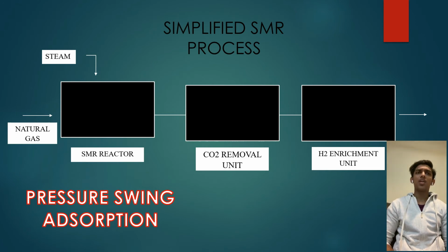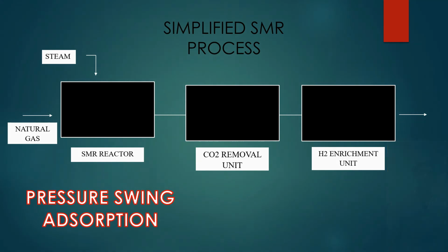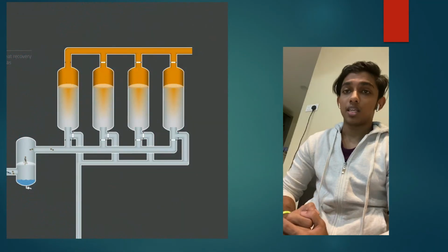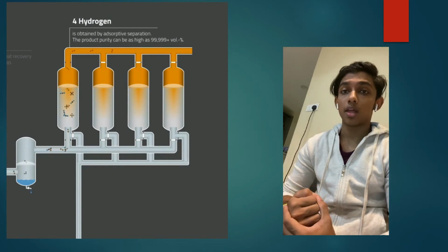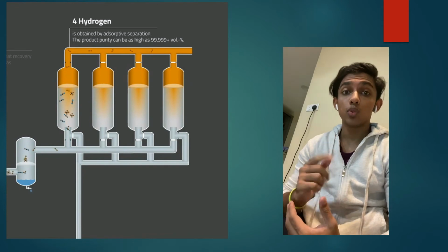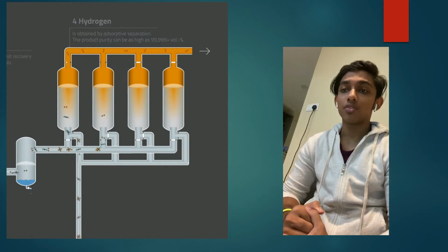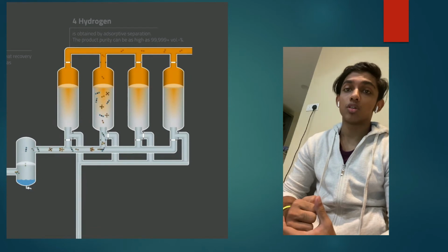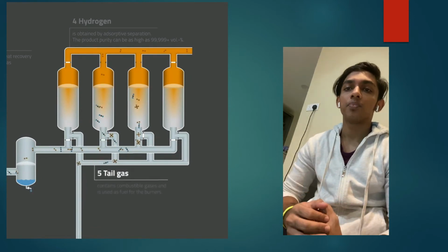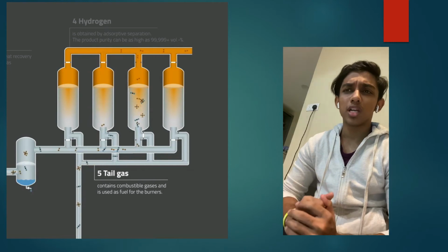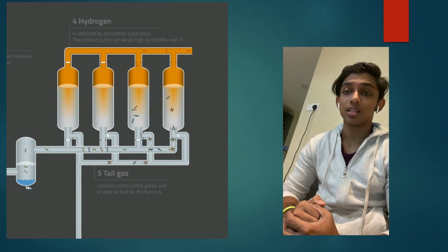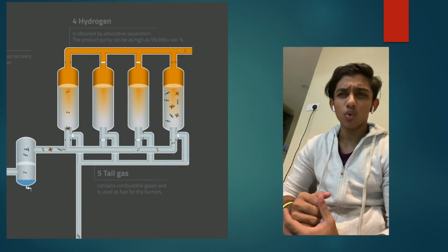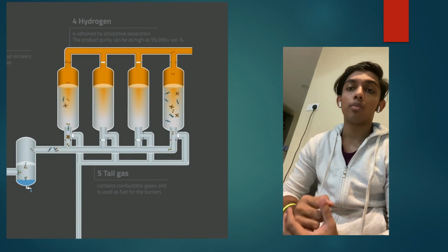So, let's have a look in detail at how adsorption works in this system. As we can see, the feed enters the adsorption tower, and the tower adsorbs the other components except for hydrogen gas, which will then be released. Components left will then be desorbed so that the adsorbent can be reused again. Lowering the column pressure, also known as depressurization, and flowing a part of the impurity-free hydrogen product gas over the adsorbent at a lower pressure, known as purging, are two common methods of desorption.